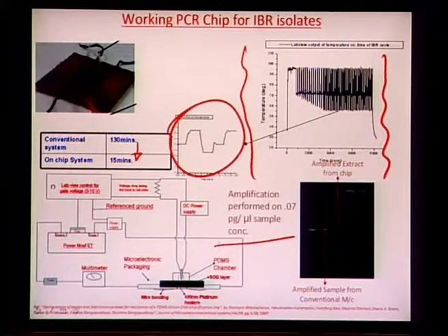This is how the control system would typically look like. You had the temperature output from the thermocouple, which would control a PID in LabView, and this is based on pulse width modulation technology, where it would determine how many times you can switch off and on this gate region, so that the current between source and drain increases and decreases over a certain period of time, and that causes the quick heating or the slow cooling, or slow heating, or the passive cooling of the particular chip.